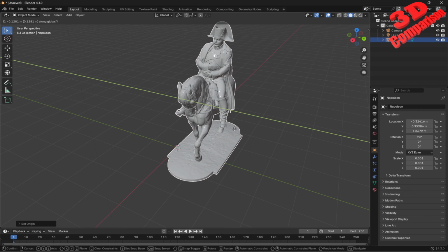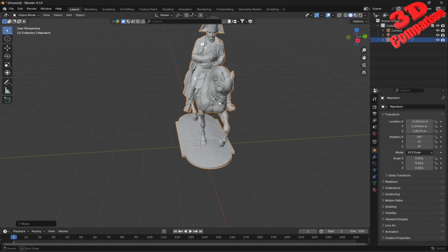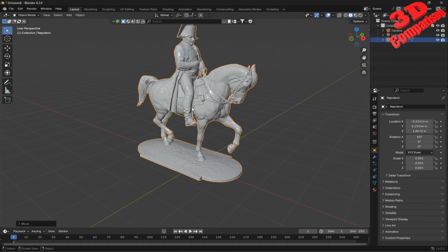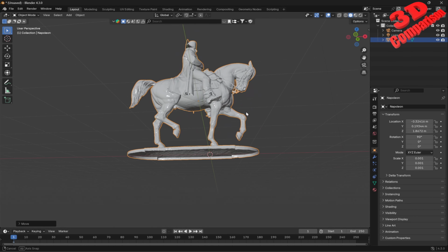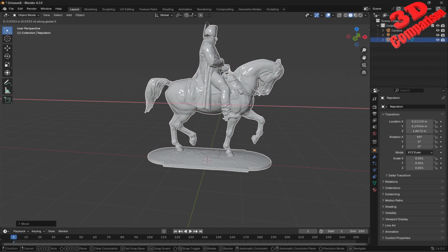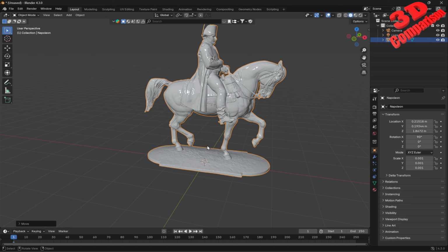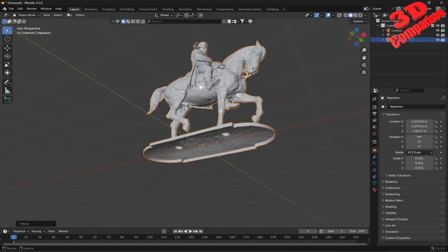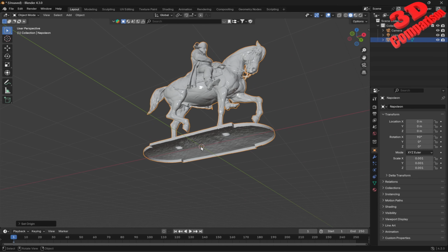And I can now move it over here. I could have moved it even without that center, but for more advanced parts, if you're going to add rotation and so on, that will control a lot of elements associated with this. Now, if I want to move that center point exactly to the middle, I can do that. I can go to Object, Set Origin, Origin to 3D cursor, and now it's snapped over there.